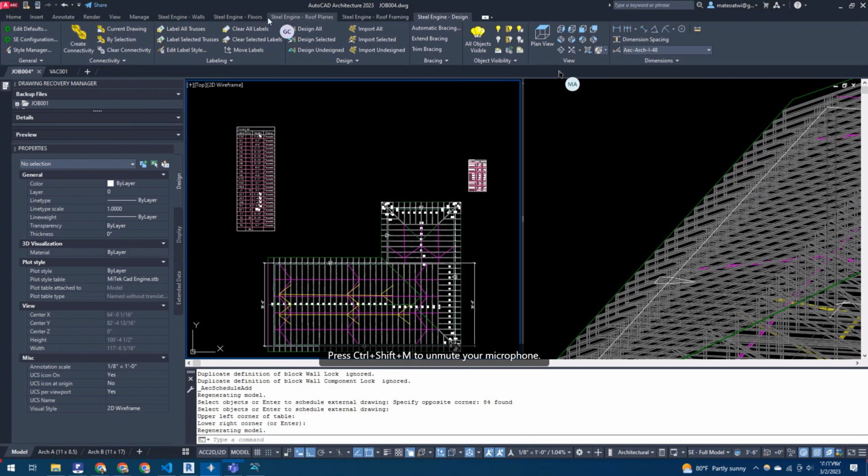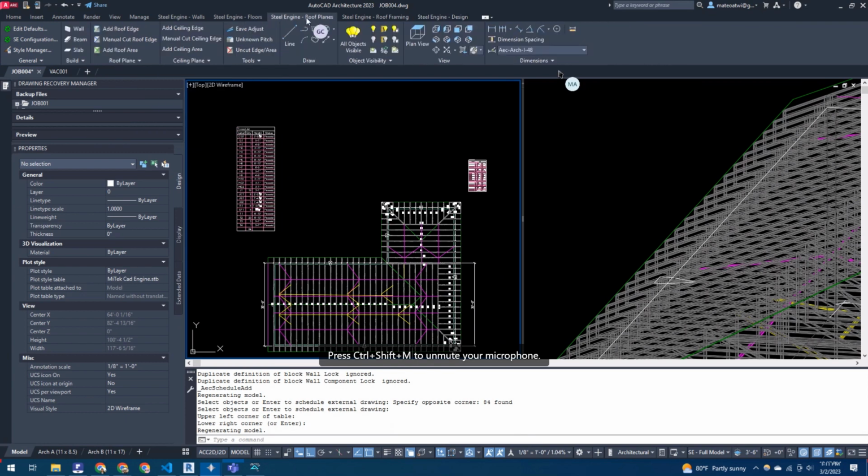So in that schoolhouse job, they have small dormers, just kind of random small dormers. So you'd have to add walls, because you got to have some kind of bearing. So you'd have to add beams or something where they're going to go, and then put planes on them and then put the trusses on them.